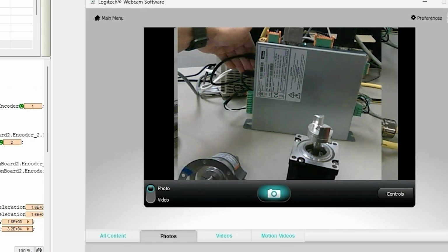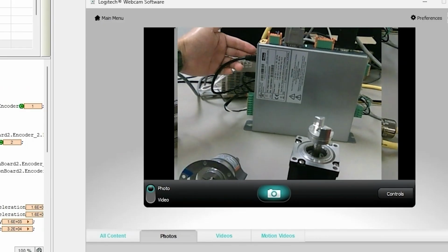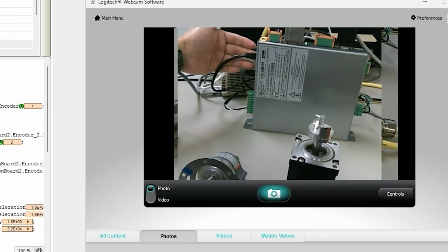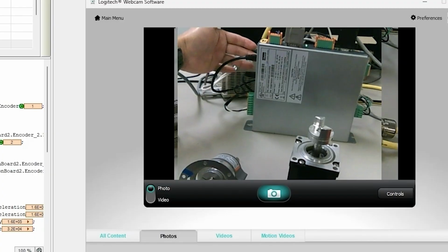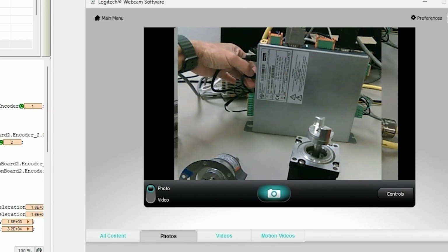What you see here also is the Ethernet connector, RJ45. That's how I program it using CODESYS, as well as PSD Servo Manager to set up parameters and commission it. What you see down here is another Ethernet, actually an EtherCAT cable.